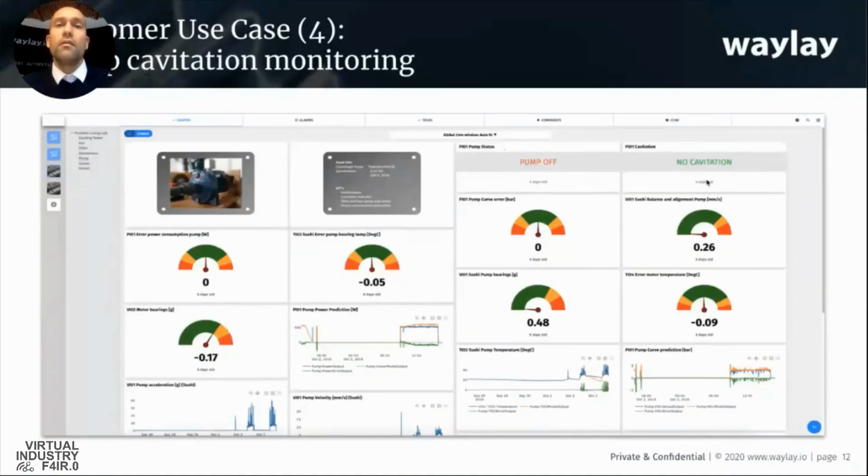we have at the back end a machine learning model that crunches through the data that we receive from that pump. And if indeed an anomaly is detected in that way, then we would see an alarm in this case. There's obviously complex logic as well by which we can take things like a pump status into account and only act upon certain things based on equipment statuses, for instance.